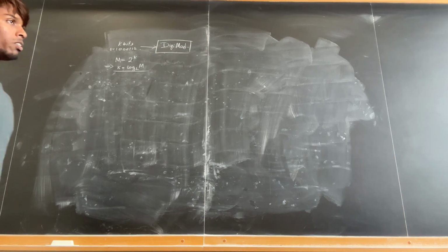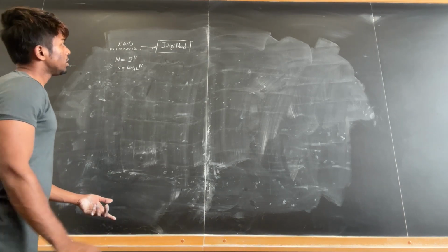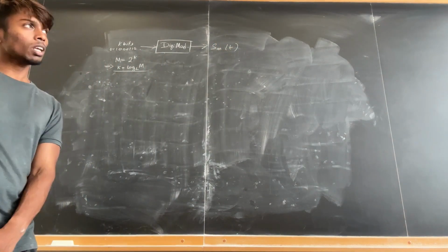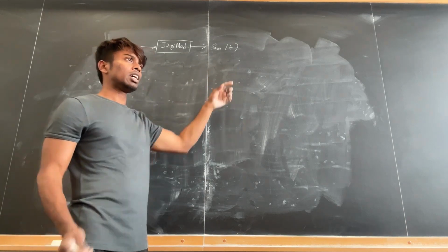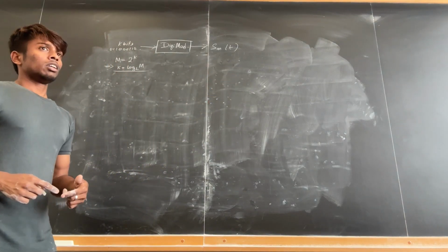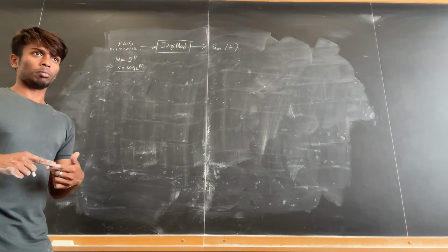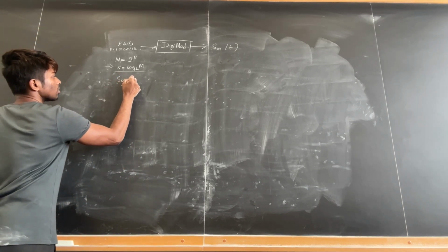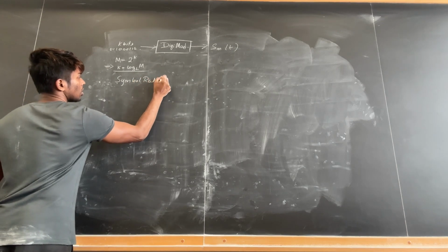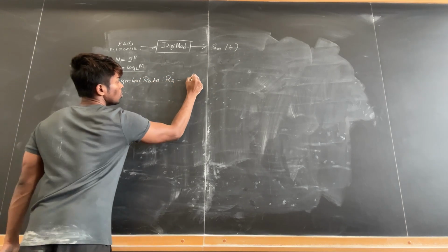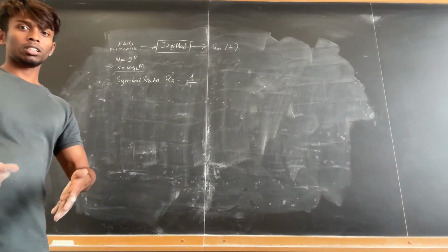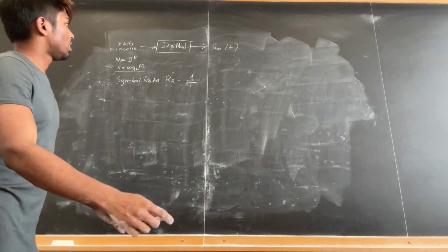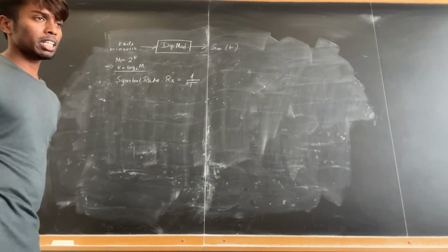So what is the symbol rate? The digital modulator creates a waveform, that is s_m(t), based on one symbol m. So for one symbol there is one waveform s_m(t), and that waveform is transferred. So the time to transfer that waveform is, suppose, the time period T. So the symbol rate shall be Rs is equal to 1 by T. That is the time period to transfer one waveform. So the entire time period of that waveform is T, and we have 1 by T as the symbol rate.